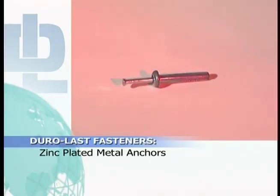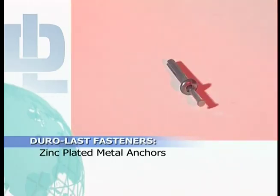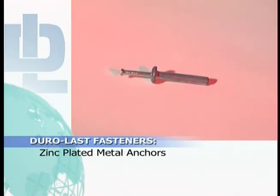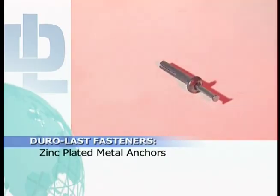Zinc-plated metal anchors are used for terminations into masonry. They require a pre-drilled 1/4 inch pilot hole 2 inches deep. These anchors are typically used with termination bars and fascia bars.